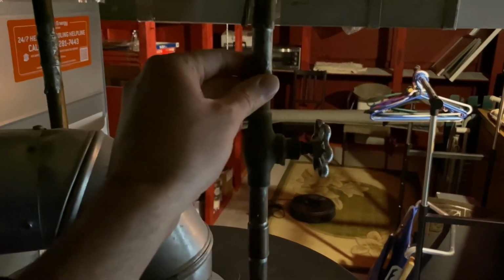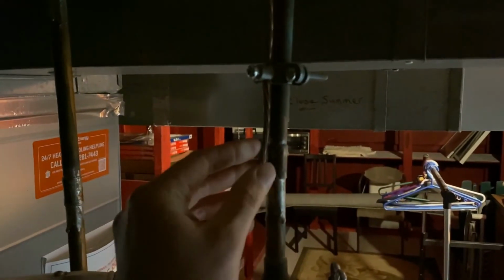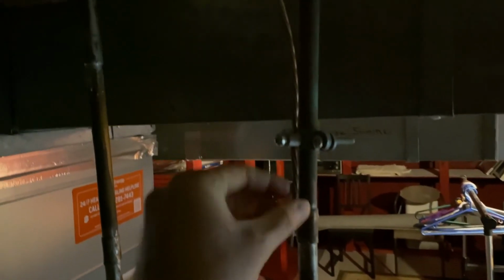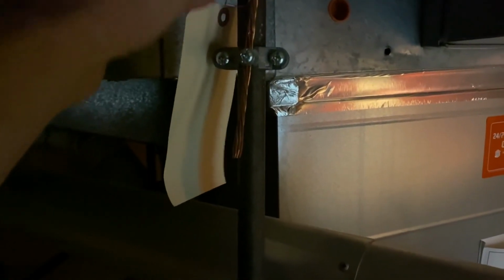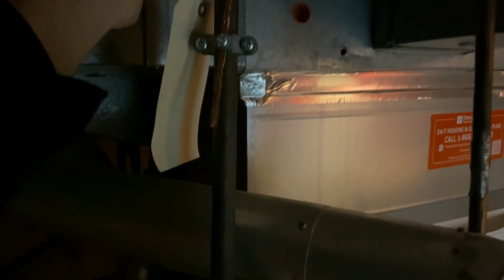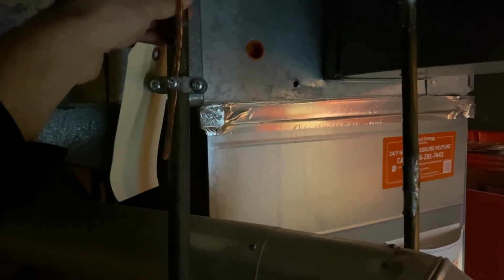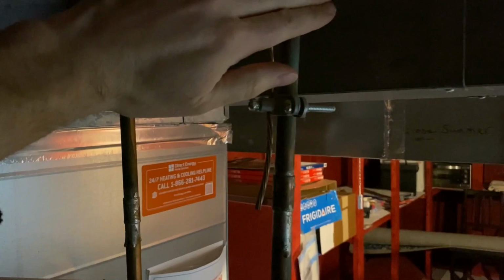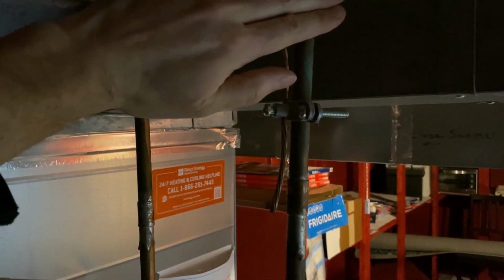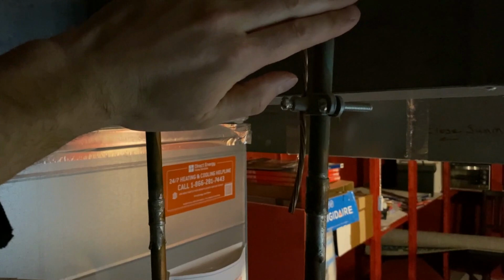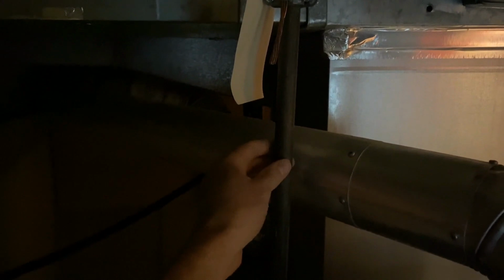And the fact that we're taking this jumper here, I know you can't see very well because it's dark down here, but here's the main cold water pipe that comes into the hot water tank. You can see we have a bonding connection here with this copper wire going over to this side, and this is the natural gas that feeds into this hot water tank. So now what we've done is made this whole cold water line's dirty electricity, that we're finding on the cold water line, we're bonding that over to the natural gas line, and we're contaminating this now too.